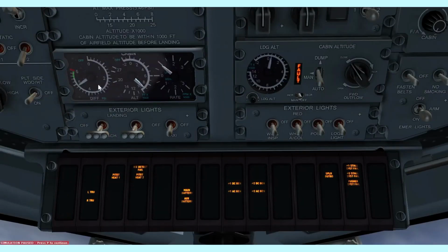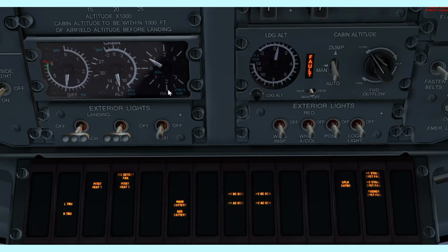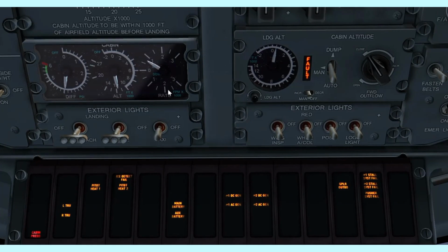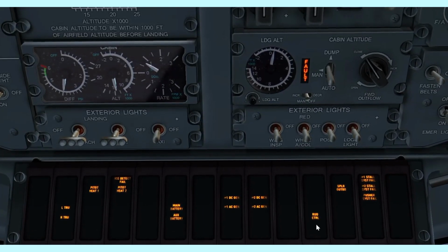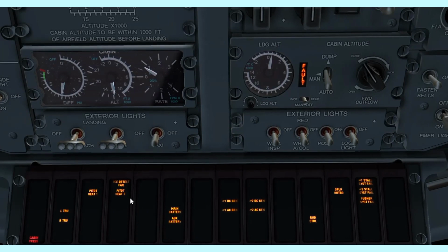Just a quick one. As you can see, as the aircraft is depressurizing, look at these gauges here just to tell you what is actually happening. The differential pressure will be decreasing, going to 0. The cabin altitude will be increasing, going quite high. And the cabin rate of climb will also increase. So you can see this is what's actually happening. If I keep the simulation on for a moment, I don't want to lose control. Let's just look at the gauges quickly to see what we normally see here, and you will be able to see that it's depressurizing, and then you can have another light coming on, and lots of things are coming on here, as we have faced a serious malfunction in the aircraft.